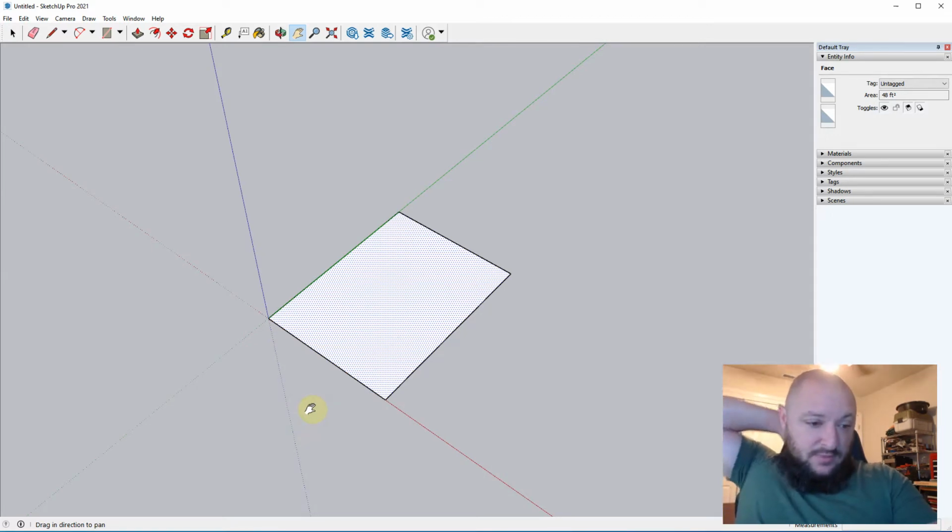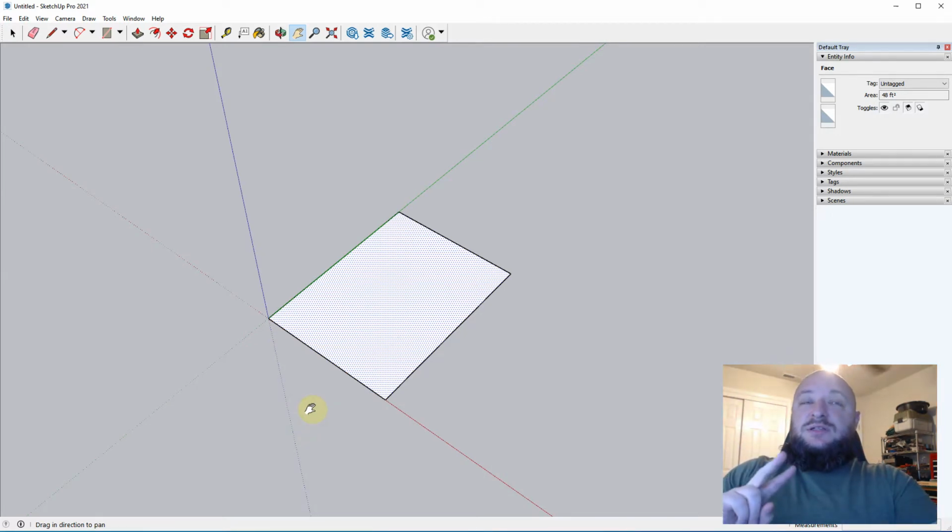Now, in this class, we're going to be using two distances, one for interior walls and one for exterior walls. Your interior walls are going to be 4 inches, and your exterior are going to be 4 or 4.5, or 4 1/4, something in there. I don't care which, just be consistent. If I start seeing in one project you're doing 4 1/4 and in the other you do 4.5, I'm going to start marking off points. Anyway, so figure out which of those values. I'm going to use 4, and then for the exterior, just use 6.